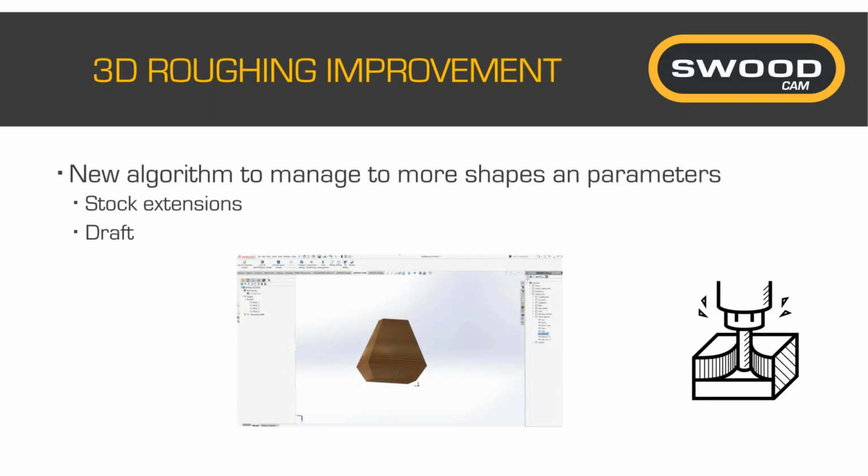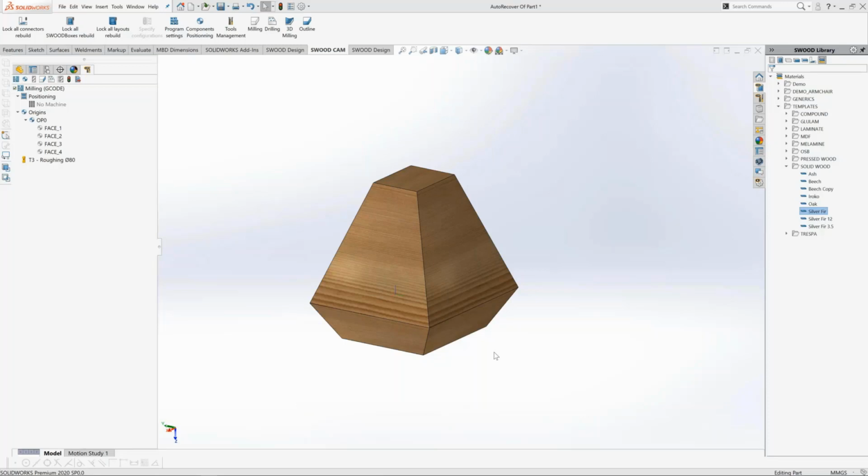So for now, we have seen many enhancements on the panel definition with the SWOOD design and the SWOOD CAM enhancements, but we of course know that our CAM solution is able to go up to 5-axis simultaneous toolpaths, and for that we have a first roughing operation that is available.